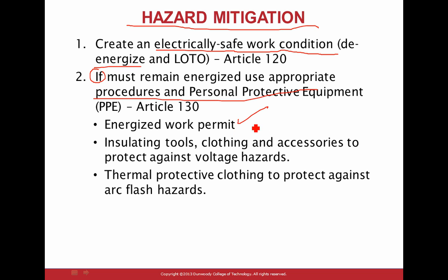So, energized work permit, but I believe you have to fill out the hazard review that you have online. After you verify the energized work permit, you have a hazard review record that you fill out, but 4 or 5 managers have to sign it, and you justify why you have to work on the energized equipment, because I can't test that piece of equipment if it's de-energized. Some equipment you can't just measure the voltage and troubleshoot.